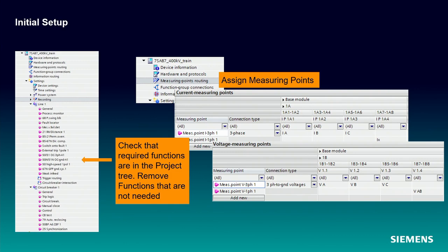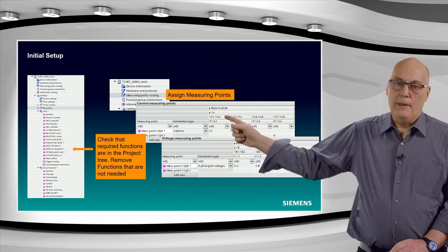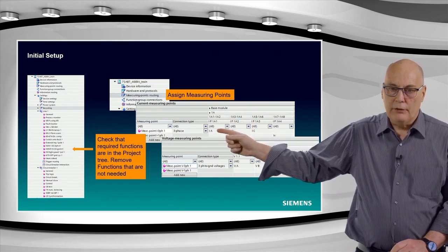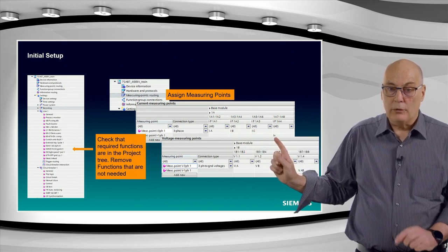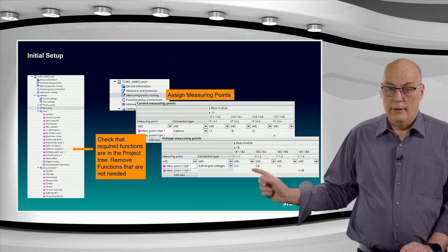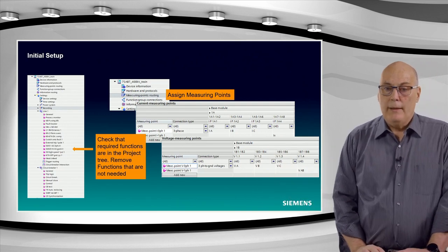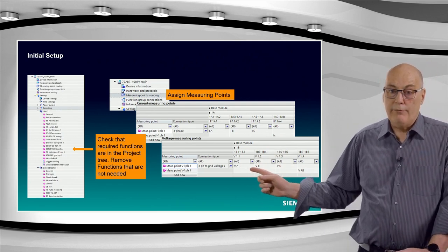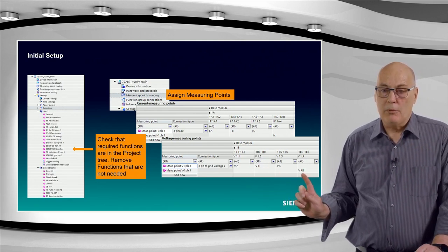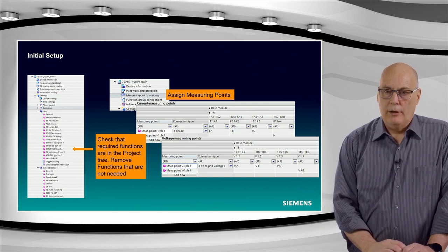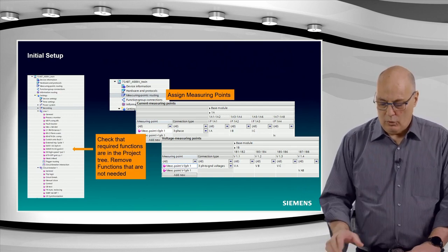Also important, if you have to really work with a relay on site, you don't need to refer to any manuals or pamphlets to find the terminal numbers. In DIGSI, you can see the terminal number of the device at the top here. There is the actual physical terminal, and the IA phase current is connected there and so on. And the parallel line residual current, as we'll see later on, is connected to this terminal here. At the bottom, the voltage in a similar manner. There is also a 3-phase measurement for the line and a single-phase measurement, probably a bus bar voltage for sync check. Not a subject we'll cover today, but I just showed it there for completeness.